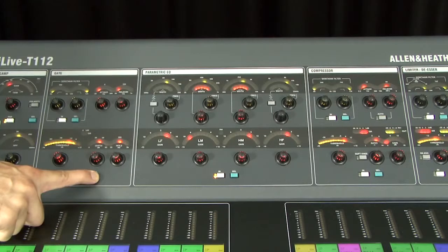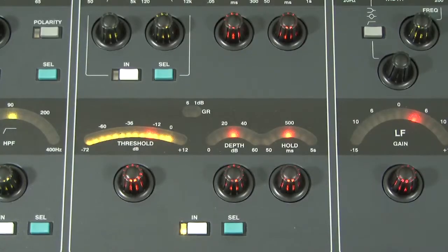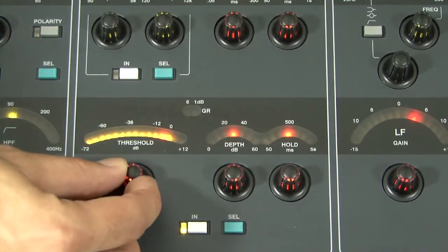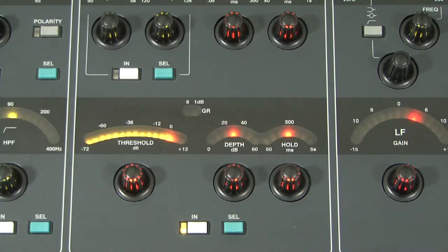If you press and hold down a processing section select key, you can listen to the signal at that point in the signal chain through the PAFL bus. These select keys are also used to copy and paste and reset sections of the channel signal processing. Signal meters are presented throughout the signal path. The 3 dynamics processor threshold controls feature signal meters that display beneath the pointer on the LED dial, so you can quickly see where to set the control.